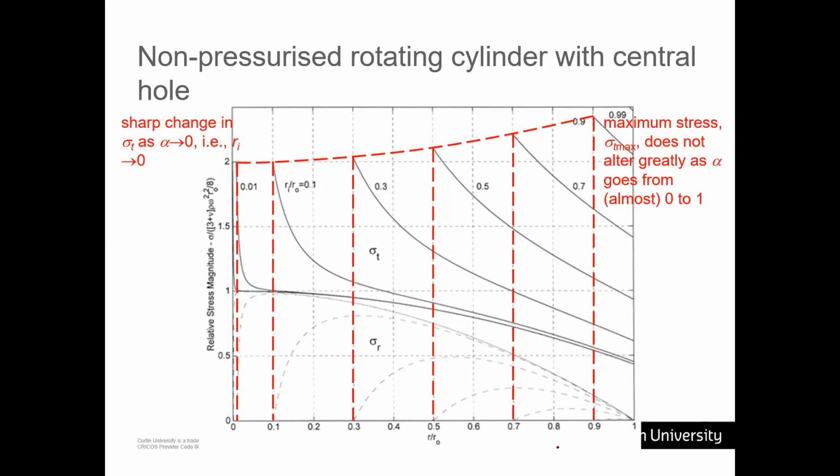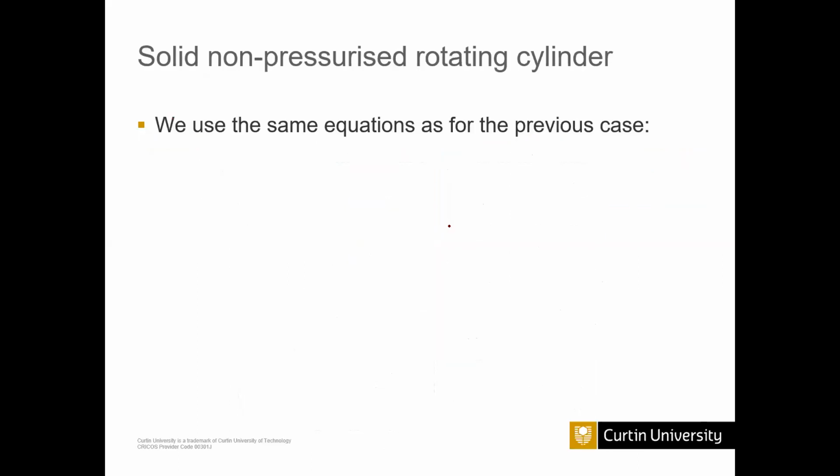That means if you consider the ratio between some specific point on the cylinder and the outer radius, if it is 0.9, this is the margin point of the thick wall and thin wall. At that point you will get the maximum tangential stress. It will reduce a little bit, but it has a certain value. It is also maximum, but not that much. So this is the variation.